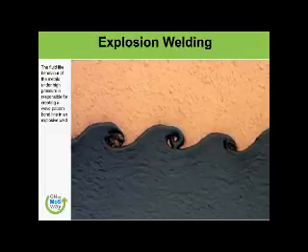The fluid-like behavior of the metals under high pressure is responsible for creating a wave pattern bonding, like in an explosive weld. This type of material is used because we need a certain type of material on the inner side of the tank, and we want a certain type of material on the outside of the tank. So this process we use for creating that.